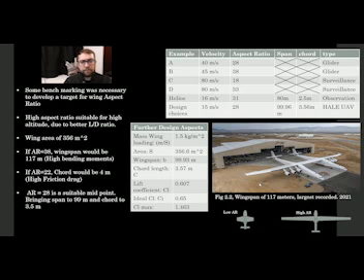For perspective, the NASA Helios had an AR of 31. Considering our wing loading and a weight of 535 kilograms, the wing area will be extremely large at 356 meters squared. An aspect ratio of 38 would create a 117 meter wingspan. By comparison, consider the structural reinforcement required on the Stratolauncher in this picture with its 117 meter wingspan.